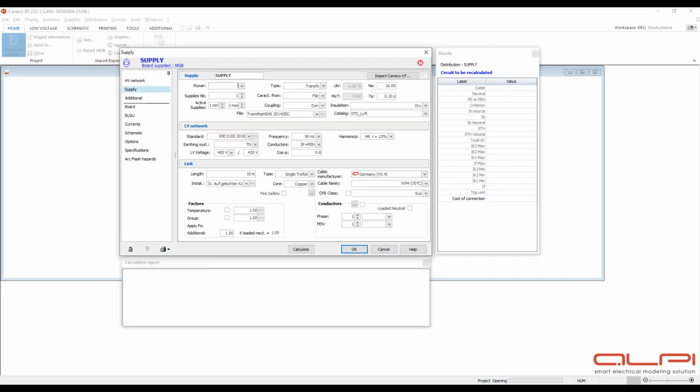So in the end, you can have the main catalogs as default settings, just not to add a new catalog to the process every time. Because usually if you start a project design, you will not choose one time Schneider, one time ABB, one time Hager or something else. But you are able to change the type of the catalog, the type of the cable, on each position. So you can have an MSB board with ABB components. You can have a sub-distribution board with Hager components and an additional one with Schneider components. And you can make a full calculation completely over all manufacturers.